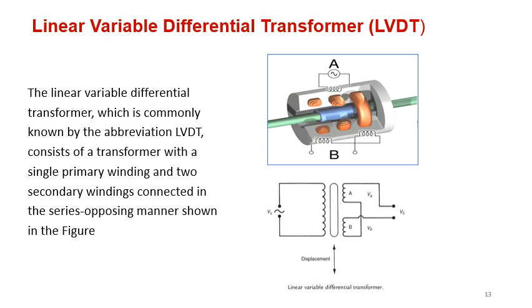Another technique used to measure the displacement or the translational motion is called the linear variable differential transformer, LVDT. This is the one you attended in the lab, one experiment you have done already on LVDT. This kind of sensor depends on the theory of a transformer.